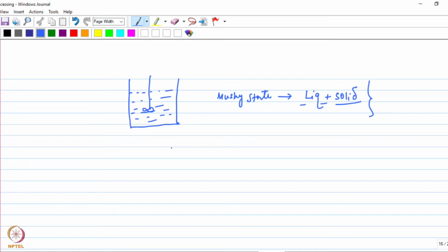Okay, and this property of a material, if you process a metal through a route like this, you basically break down the dendritic structure and you can expect an equiaxed microstructure in the solidified material, if you do this stirring in the two-phase region.